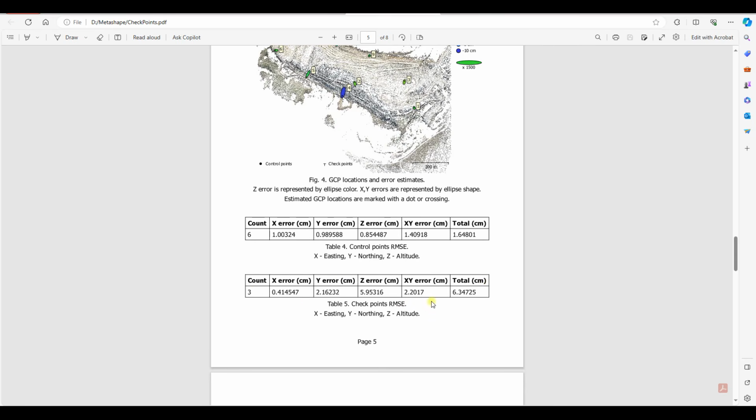So please, a word of caution, look at those values in those reference settings. Make sure that they are something that is representative of reality, not a false 5 millimeters. It is very, very rare to have any control points in this day and age that are actually accurate to 5 millimeters, unless your surveyor has done a full network calculation.